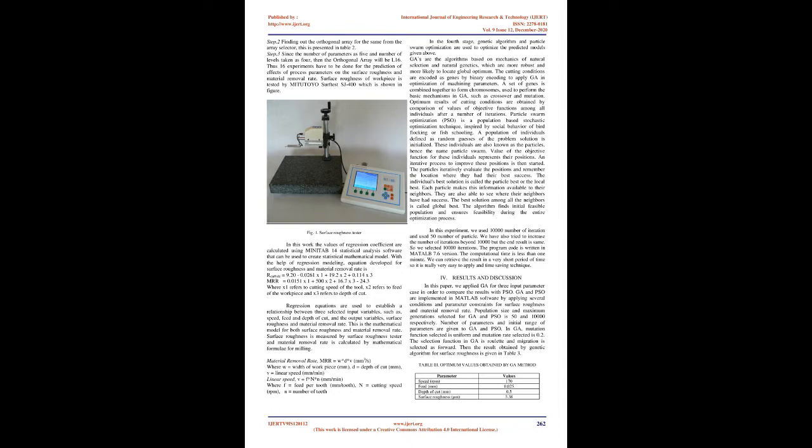In the second stage, the data has been referred from the work done in a vertical milling machine. We used mild steel bar as workpiece and tungsten carbide, grade P30, tip as cutting tool. We conducted experiments using 3 input variables, namely cutting speed, feed, and depth of cut. The ranges of the 3 parameters considered are given in Table 1.